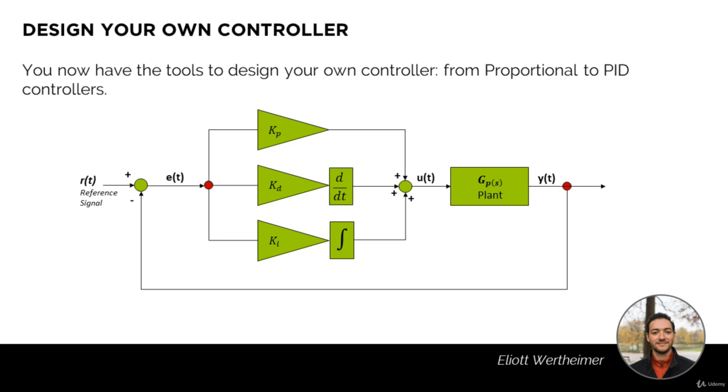So I just gave you here a block diagram of a more conventional PID controller than what we saw in the first slide of this lecture, the one used for the Ziegler-Nichols method. As you can see, it is a conventional closed-loop system with the reference and the output building the error. And then we have three clearly delimited branches, one for proportional control, KP, one for derivative control, and one for integral control. They are then summed into a control signal, which is then fed into a plant.